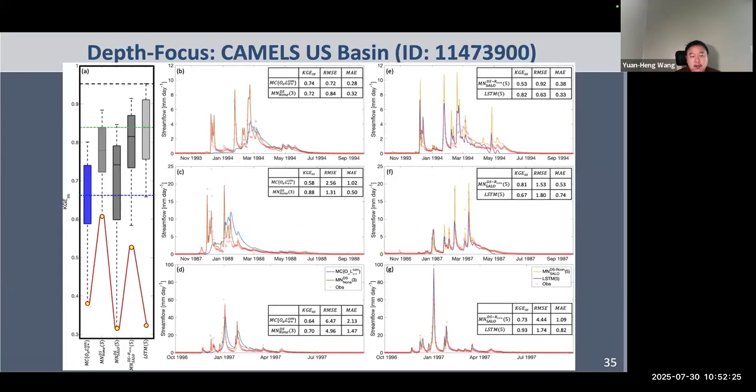Here I found one catchment near Sierra Nevada to further explore the performance and the interpretability, because this catchment has snowpack during the winter. You see from the box plot on the left showing the annual scale KG distribution that the 5-node case with information sharing and PET constraint performs pretty badly compared to the same architecture with the PET constraint relaxed.